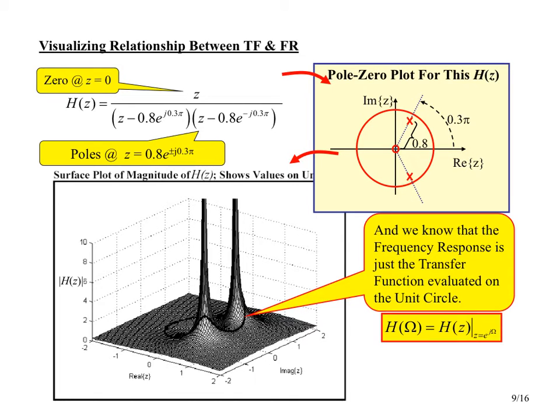So in the denominator here we've got two complex conjugate roots, and I've written the poles in polar form. No pun intended there, because that's how we like to think about pole and zero locations for discrete time. The magnitude and the angle of these things will be of most importance to us, and you'll kind of see why in just a minute.